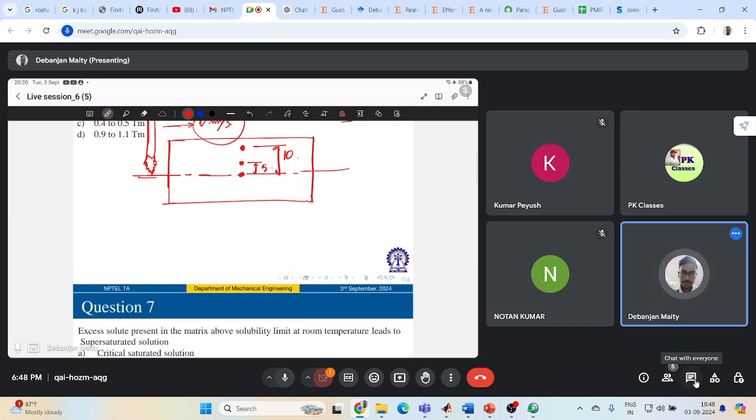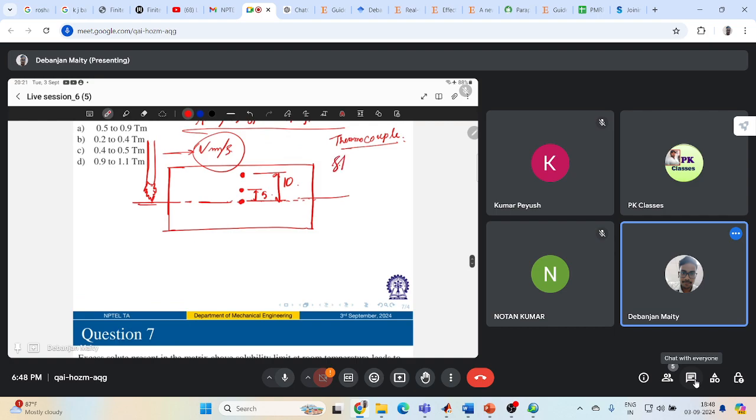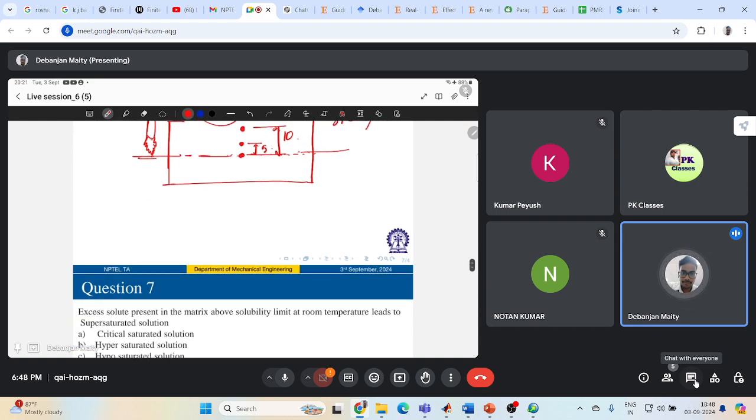So except for the initial and final transients of welding, heat flow in a workpiece will, if the length of your workpiece is sufficiently large, at each point of your center line feel some steadiness. So each point of this center line will feel the same peak temperature.